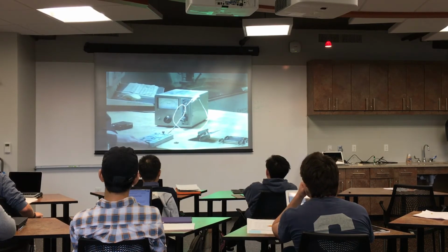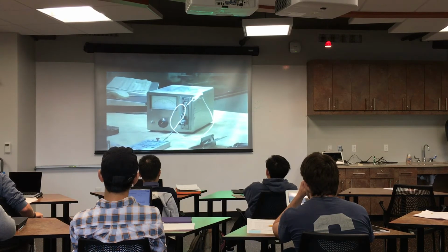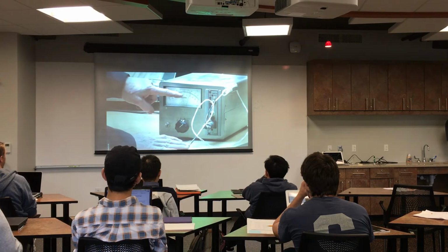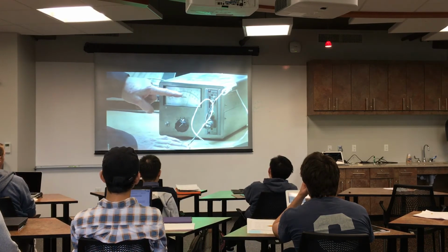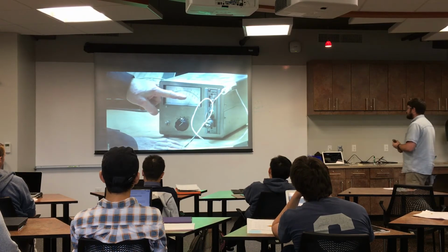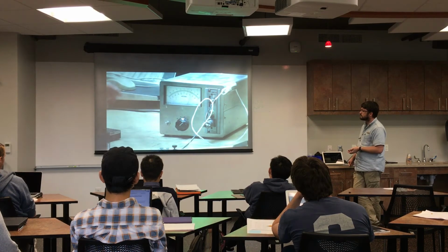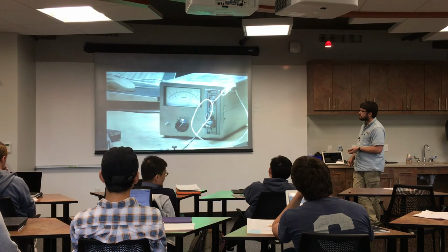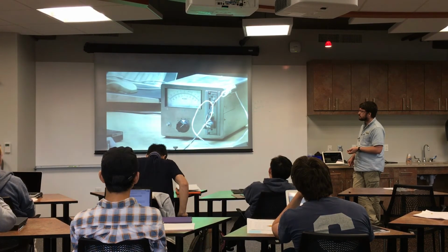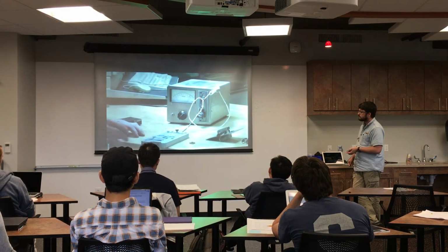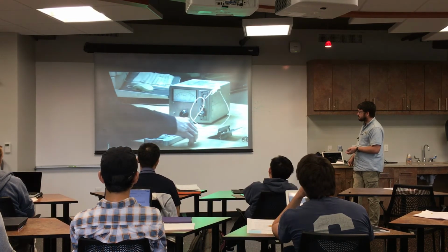You can see that because it's made of aluminum, if I put it somewhere and just put my hand over it without touching it, it drifts from the radiated heat from my hand. It drifts by something like 100 nanometers just from the radiated heat. When I take my hand away, it drifts slowly back. So it's slower one way or the other. Obviously this is not designed for this kind of stability, but the principle, the layout, is classic flexure. You can make those at any size, of course.